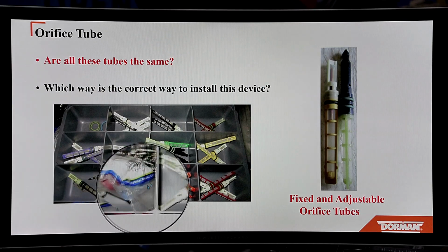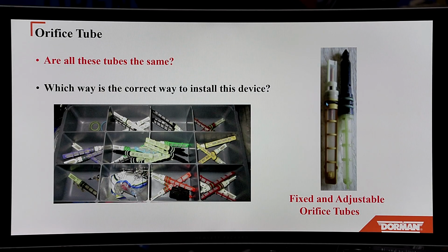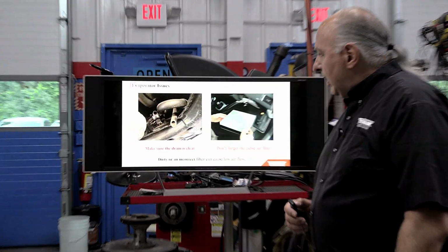And by the way, if it has 2 O-rings versus 1 O-ring, that is also different. And lubricate the O-rings with what? Oh, that leftover vacuum oil. You don't want to use PAG oil. PAG is an alkaline. It can burn your finger, and if you rub your eye, it's going to burn. Not good, right?